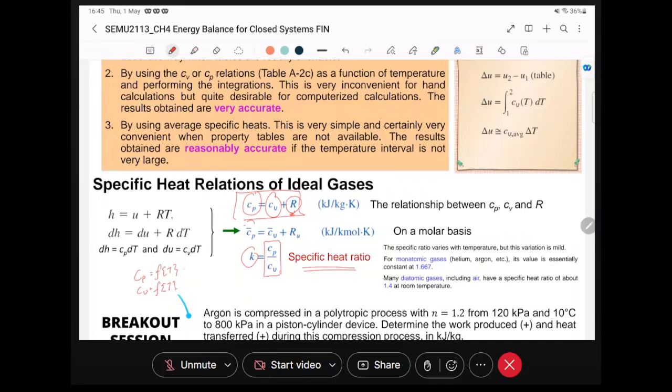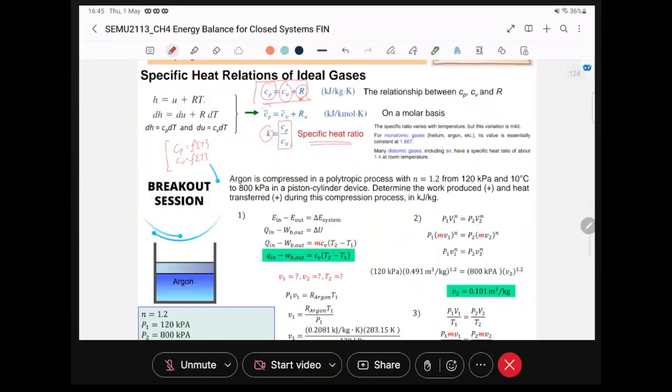But for ideal gas, sometimes the temperature plays a role in the value of Cp and Cv. Because as the temperature of the substance becomes larger, if it's ideal gas, of course, it's gas, the molecules will be further apart. So to heat up 1 kilogram of the mass, now it might be lower, it might be higher, the Cp value. So it will not be exactly the same.